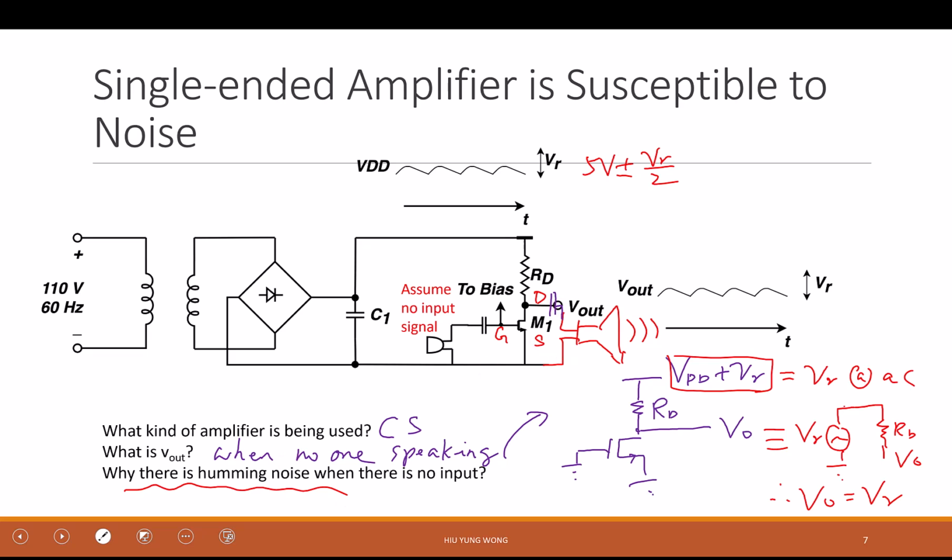So there is a problem, right? This is just your ear. Maybe you don't care about this noise. Everything works well. But when you go to a high precision system that you really need to use to do some control, then this noise is going to hurt you. How can you cancel this noise? And that is the reason we use a differential amplifier. And we'll show you why.